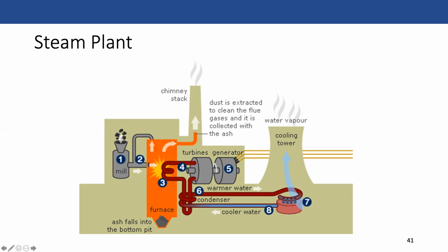The steam or water that comes out of the turbine isn't cold once it comes out, right? The turbine is only able to take advantage of some proportion of that heat, and so that's another source of the efficiency loss: you're not able to extract all of the heat energy that you would want out of the water.